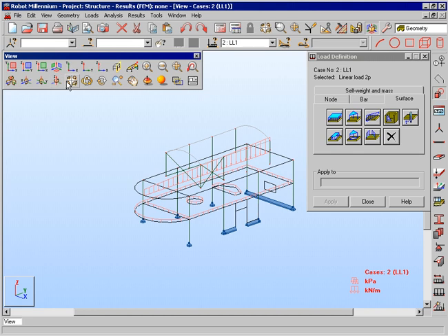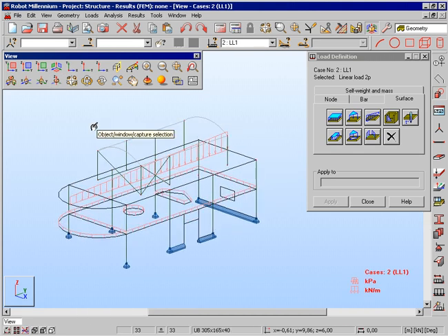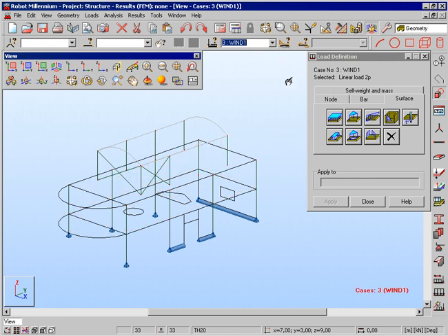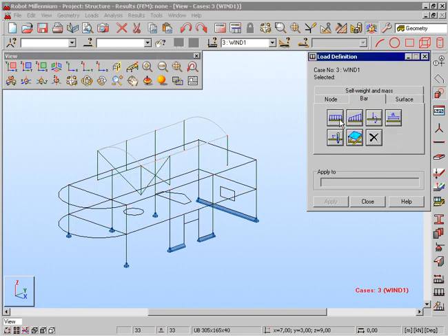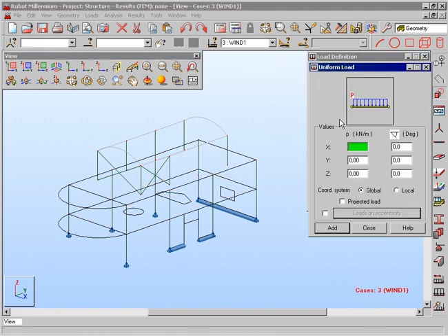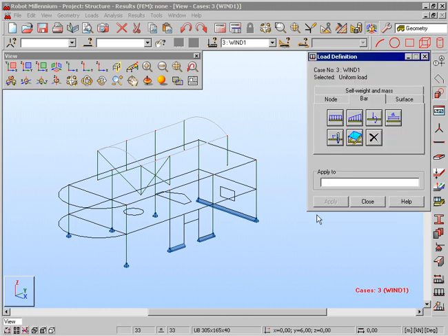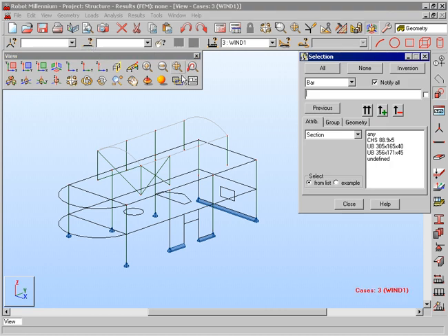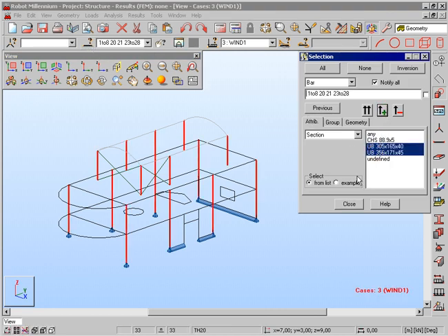Note how we apply all of our line loads and all of our loads onto the geometry of the structure. There is no need inside Robot to apply those loads directly to finite elements, because the program takes care of the application of the loads to the elements inside the software. Therefore, the user only need define the loads in the real position on the model.